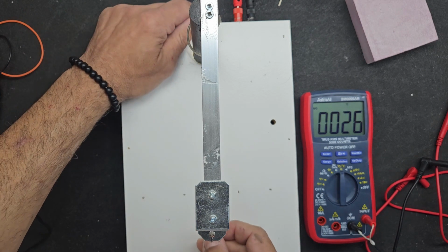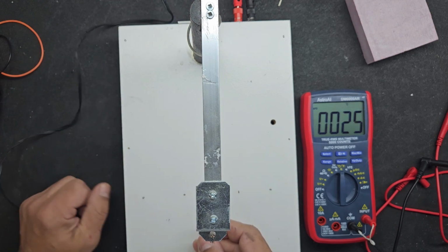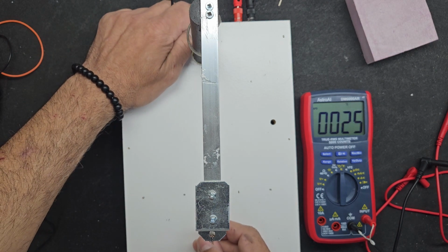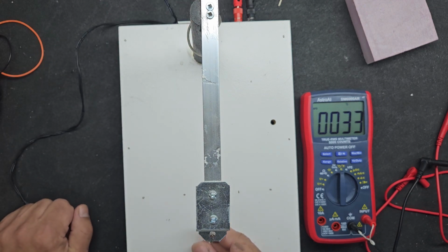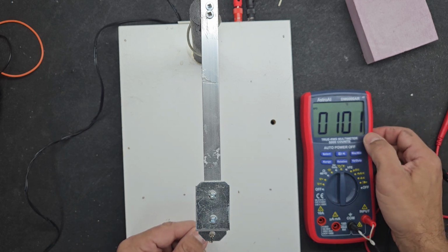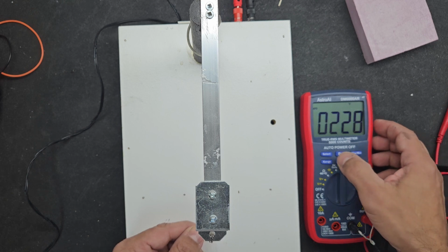Right, let's turn it on and let's see how the temperature changes as we're passing a 5 volt 1.5 amp current through this nichrome wire. It should generate heat. It should start to heat up. We're at 25 degrees right now. So as you can see, the nichrome wire is resisting the current flowing through it, so it's heating up here. We're at 100 degrees Celsius, 230 degrees Fahrenheit.